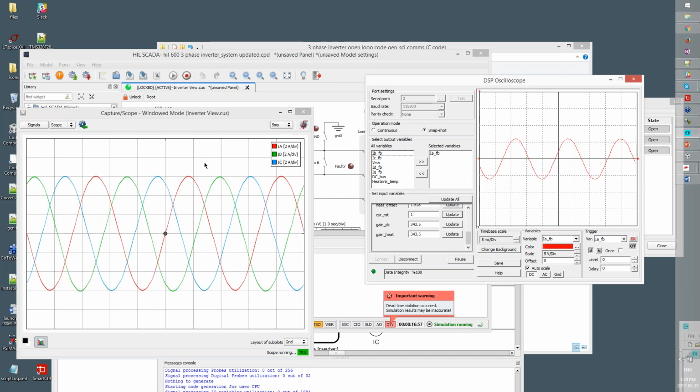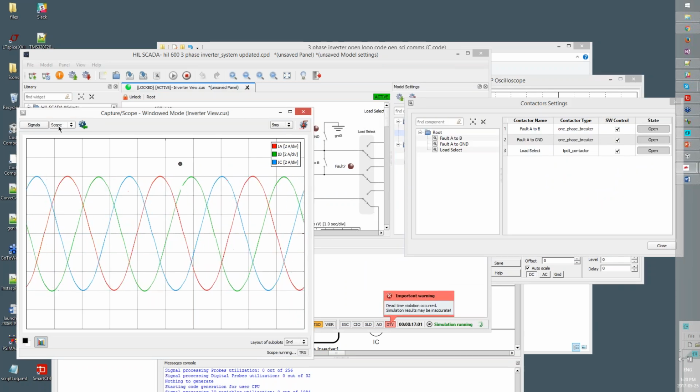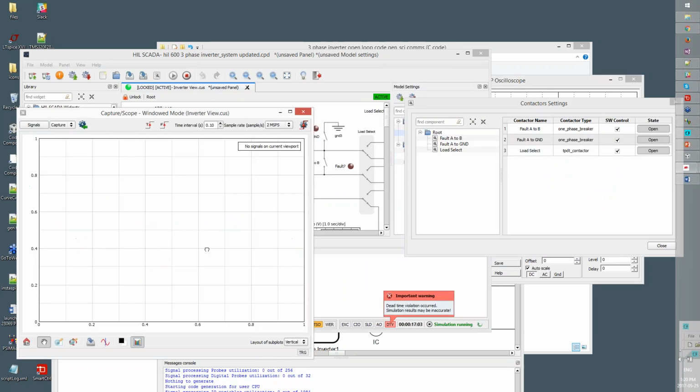You'll see on the left side you've got your scope, so you want to switch that to capture. Scope and go to capture. And then hit that little cog with the green arrow. This is going to import your settings from scope to capture. Now just go ahead and set up your trigger. Top right arrow with the cog. So this is your trigger.